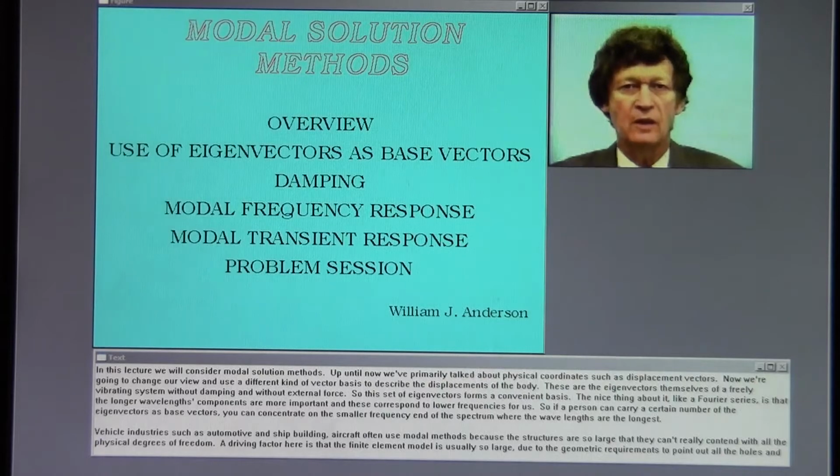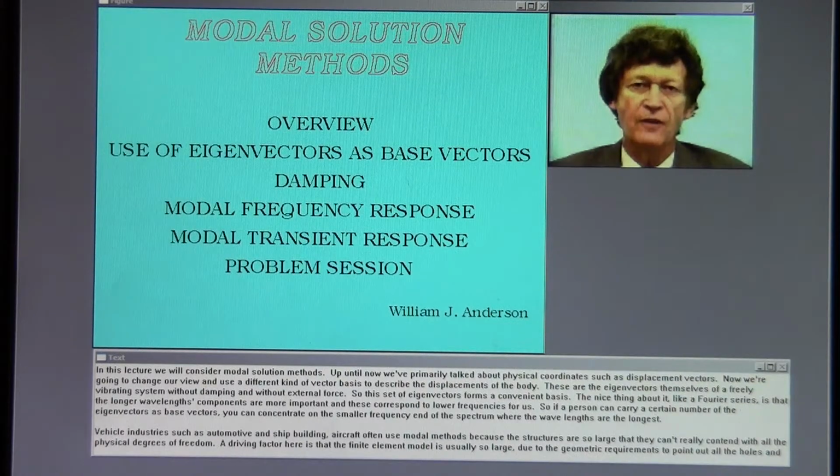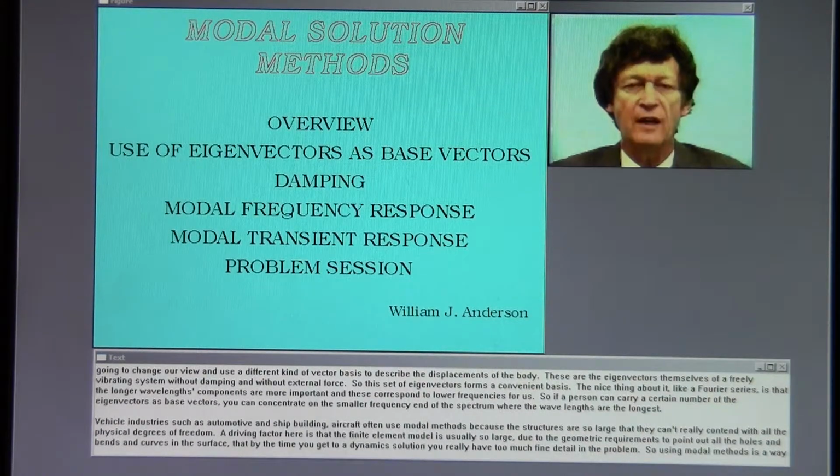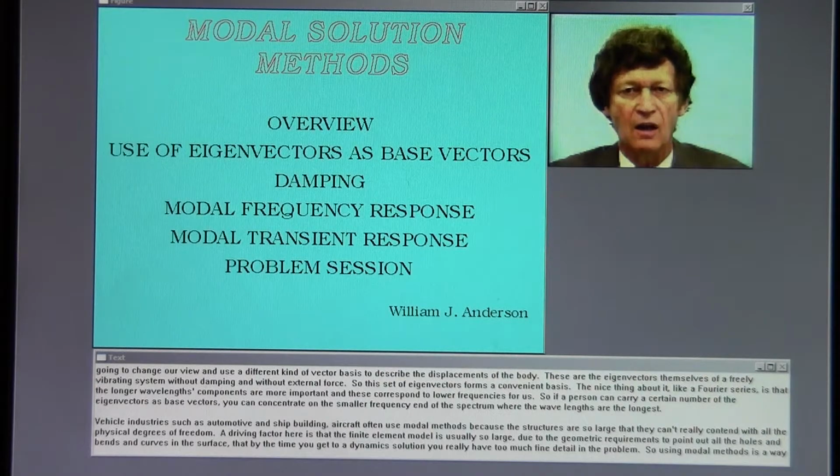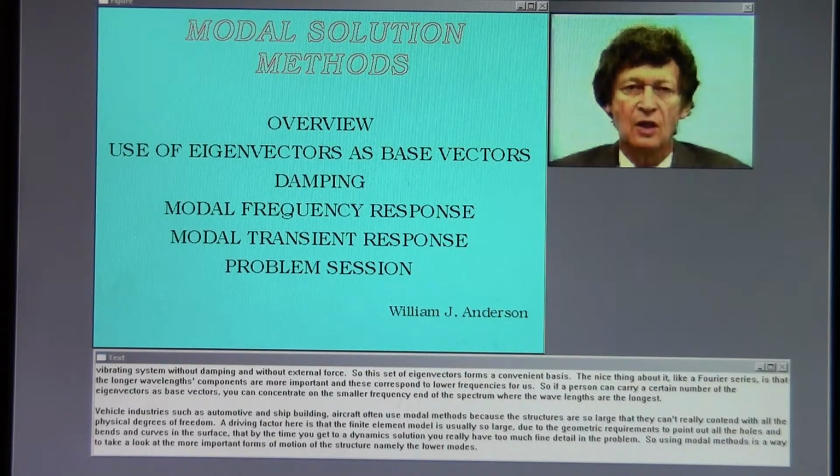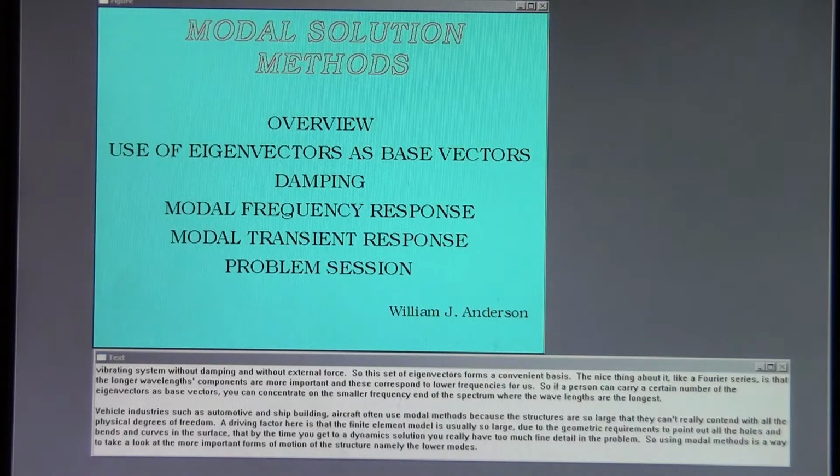In this lecture, we will consider modal solution methods. Up until now, we have primarily talked about physical coordinates such as displacement vectors. Now we're going to change our view and use a different kind of vector basis to describe the displacements of the body. These are the eigenvectors themselves of a freely vibrating system without damping and without external force. So this set of eigenvectors forms a convenient vector basis.